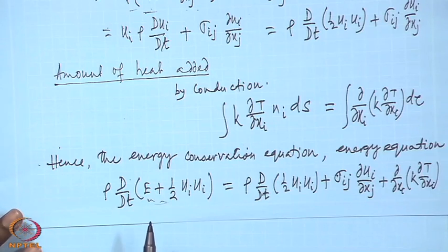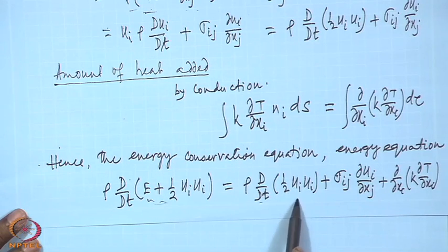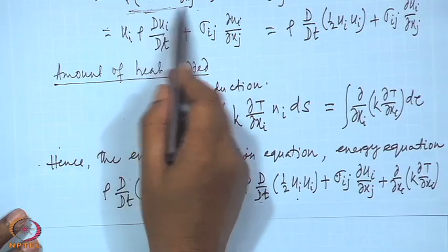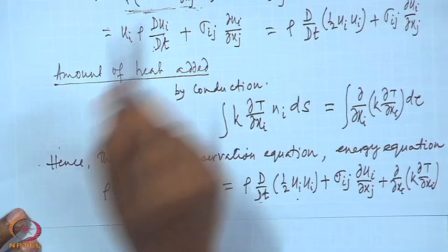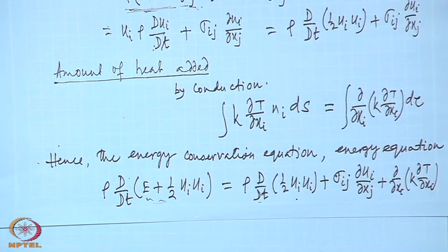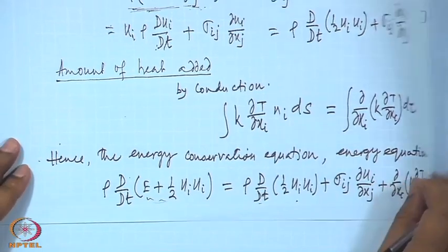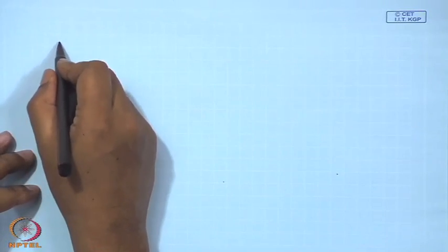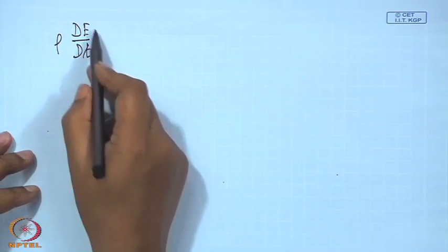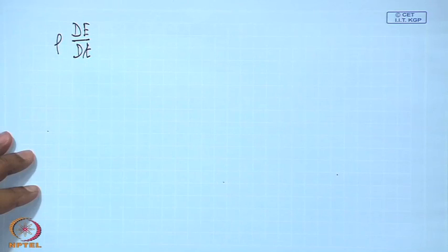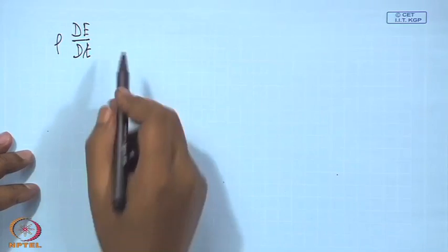And also in many cases, instead of coming to this form, these two parts are kept like this without doing this addition. So, in various forms they are expressed, but here we will just cancel them and write it in this form. The other forms we will not be writing. So, we have here the rate of change, and this itself contains that convection. Okay. So, convective transfer of temperature is not required separately.